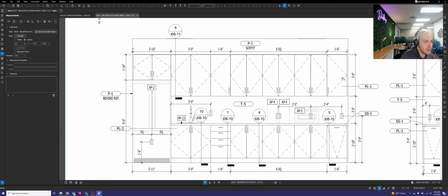And one other thing before we get too far, I will get back into the materials with you, but we also need to make sure what's happening here at the top of these cabinets. As mentioned when we looked at the cabinet blocks, if you have drywall or a soffit above your upper cabinets, you do want to put a reveal in between the cabinets and the soffit or the ceiling. That reveal will be 3/4 tall, and it'll run the entire length of this cabinet area. But if there is no soffit above these cabinets, or there's nothing blocking the cabinets from being lifted off, a reveal is not needed there.